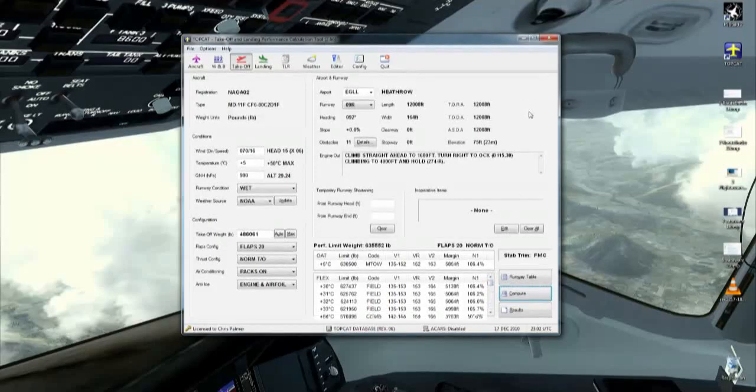I will therefore elect as pilot in command to conduct a full thrust takeoff, which will really allow us to rocket out of here. I have little doubt that we would be able to get away with a thrust reduction. However, it is not by any means necessary. We will cover assumed temperatures in more detail on the following flights, but for this one, we will keep it simple and select the top value. This will give us a very healthy 5,920 feet stopping margin, nearly half the length of the runway.